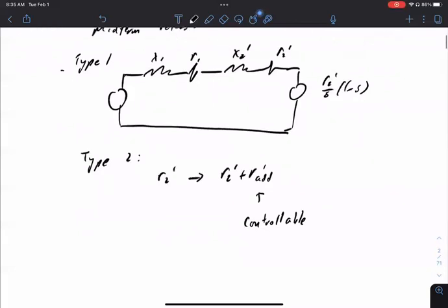So anybody remember what the drawbacks for type 2 was? You can change operating range by changing this R add prime. But what are the drawbacks with this strategy? Okay. It's low efficiency, right? One is low efficiency, because this added resistance is always used. So this is not like a resistance added for safety reasons, where you use it for a small period of time. Here you have to always add some resistance, and then you have some loss in power, right? So low efficiency.